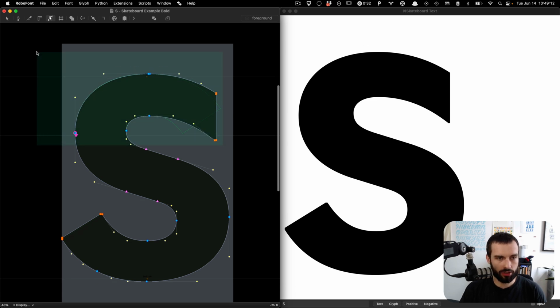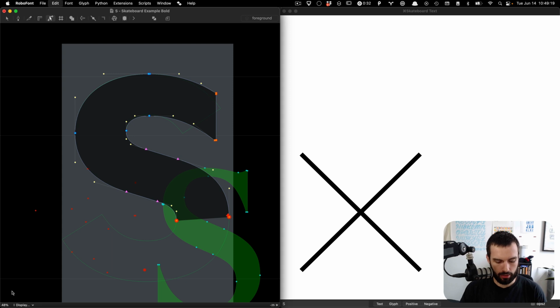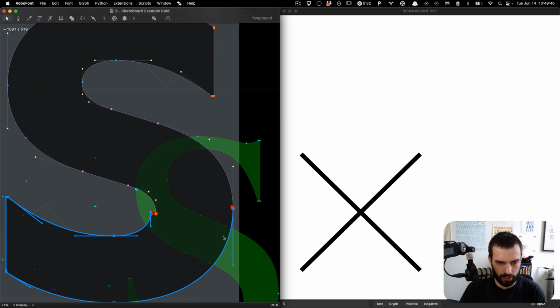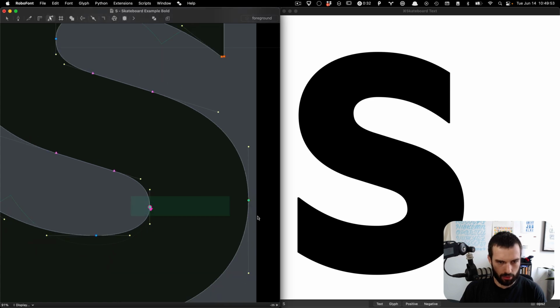And to have a similar structure down below, let me just lop this one off. So I'm going to hold Option Delete, paste the top again, go to Transform, hold Option, and click to rotate. And then I'm going to scale this over and scale this over to be maybe approximately where we had it before, using the background to guide myself. And then I can just shuffle it to connect that and connect this like so. And then maybe get these to be smooth on the bottom.